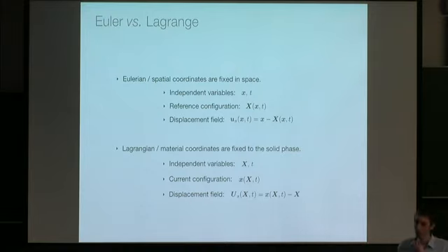It makes it sound like you're only going to be able to describe the initial deformation. If you want to go to large deformations, it seems like you need to be able to start from a general initial condition. So one of the funny things about large deformations actually is that you almost always need to reference back to a relaxed initial state. So you always need to have an initial state where the stress is 0, and that's what the displacements measure everything relative to. So that initial state can be homogeneous, and then you can do whatever you want after that. And so you can have intermediate states that are not uniform and that are not stress-free, but they're relative to a stress-free initial state. And I'm assuming that that initial state is uniform.